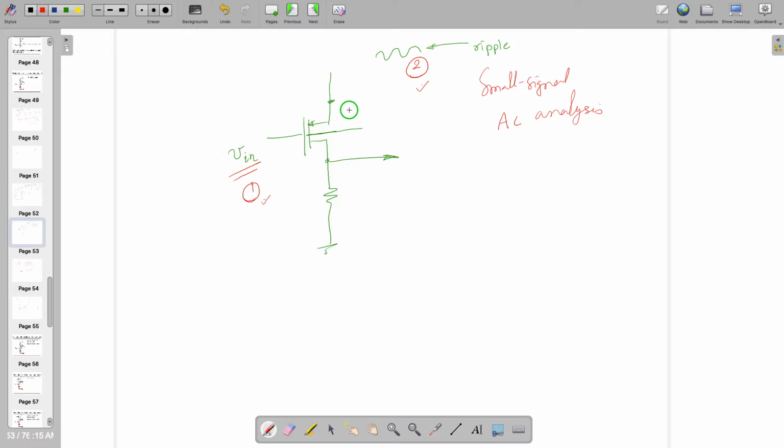There are two voltage sources. Rahul, please listen to him. So, first we will apply Vin and neglect the other voltage source. Yeah. So neglect means you are going to make it zero, right? So right now, the other voltage source is not there, and I am going to measure the output, right? Let's call that one Vout1.